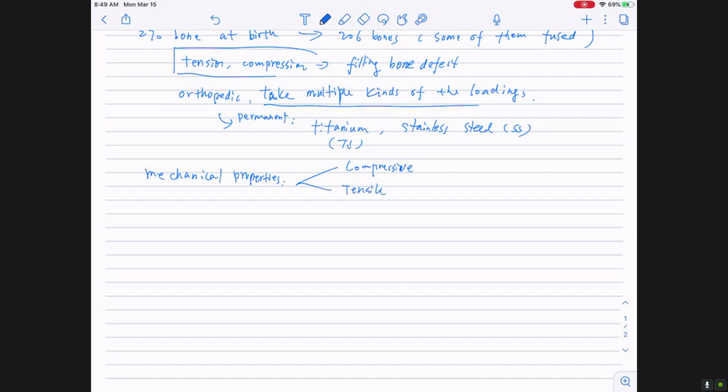So we know the stress equals the elastic modulus times strain, and the strain is generally delta L, the change in length over the original length, and the stress is the force divided by the cross-section area. So here we have one classic figure. First is the elastic region, then it starts yielding, a nonlinear area, maybe the necking area for metal materials.